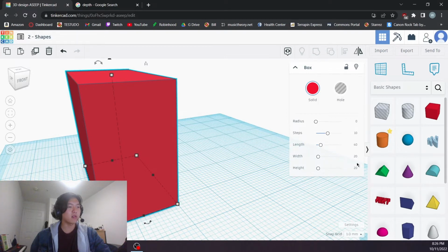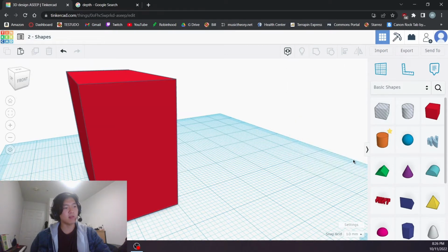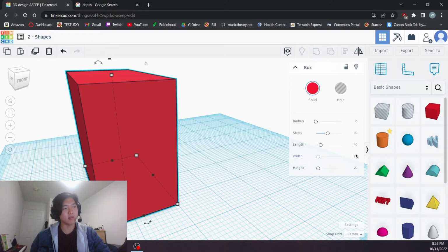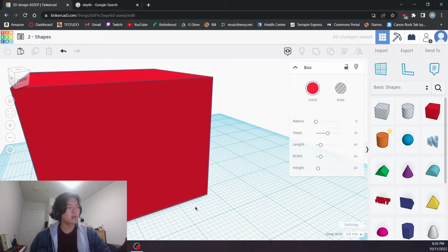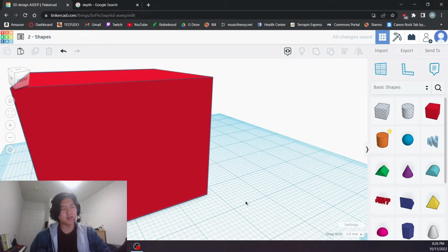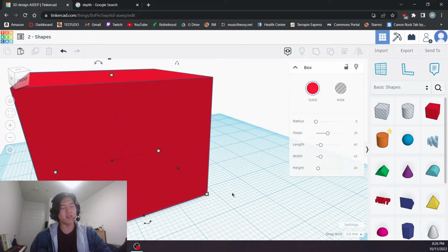What this does essentially is a scalar. Whatever dimension my shape is right now, it'll increase it proportionally. So 20 you can think of as 1. If I go to 40 for my width, what was this one? Let me click, 16. If I go to 40, that's now going to become 32. It's not too bad, but again, it's a lot of extra steps for no reason.